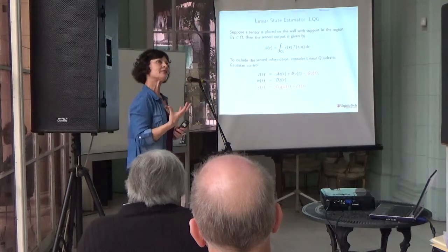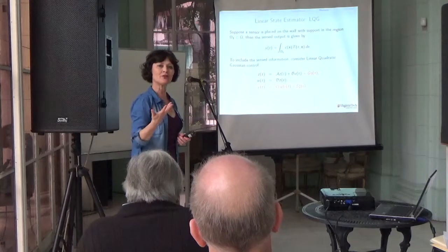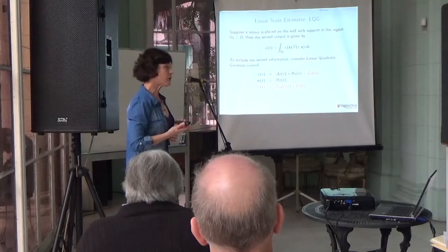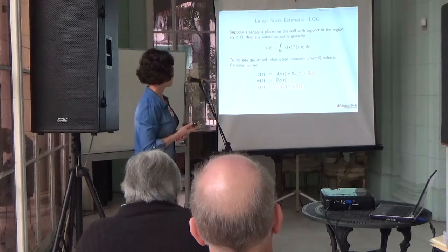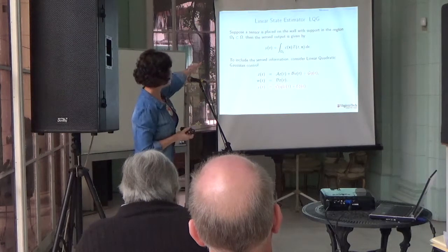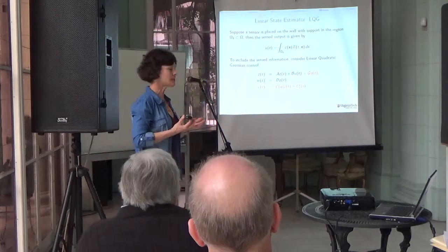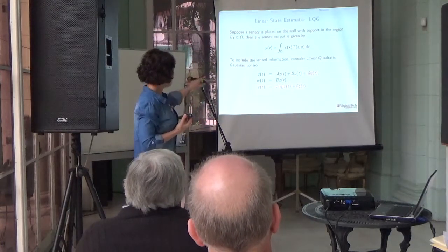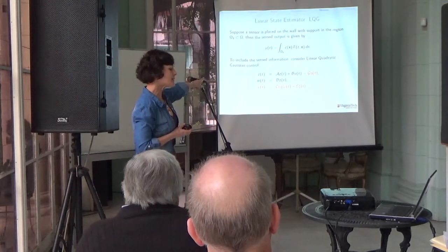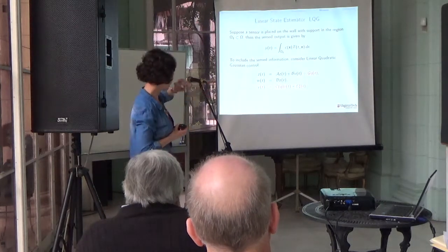Now, if I have sensed information and I no longer know the temperature everywhere, then my previous formulation no longer works because I never allowed sensed information to come in. So a good approach to this, still in the linear format, is linear quadratic Gaussian control. This formulation takes a measurement y that will be sort of an average temperature measured over an average region. And we will take that measurement and estimate the state from that and use that in the controller. I will show that on the next slide.